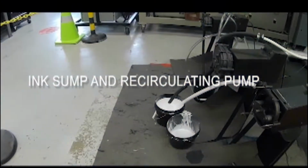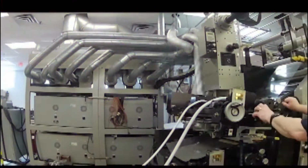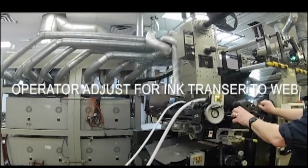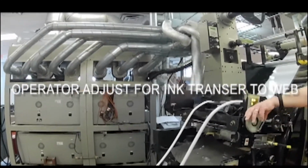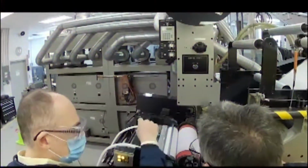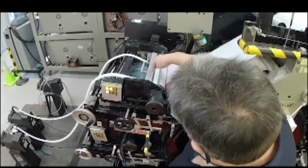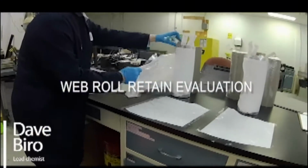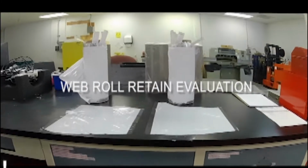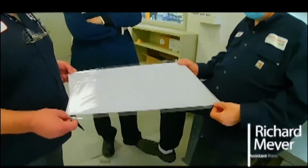With the rewinds, we're able to flag the rolls and study the inks accordingly. Here we see we're studying the inks with a banded Anilox, so we can evaluate laydown, transfer, cure, and opacities at different film weights and press speeds. The rolls are evaluated offline by several chemists and technicians. This way we can study different inks and chemistries and end uses.